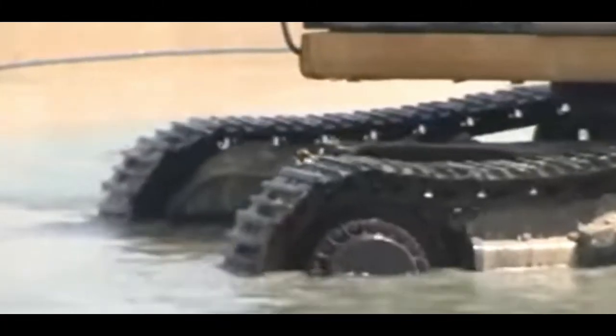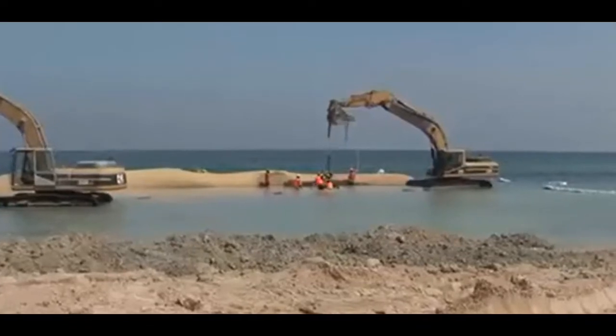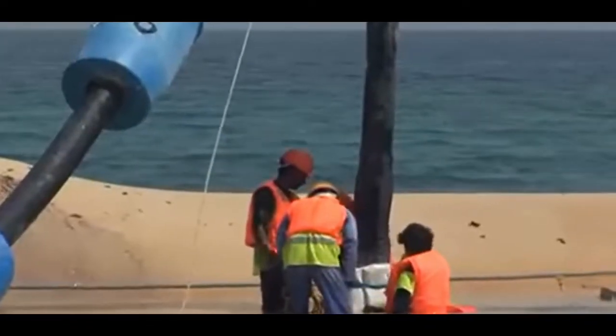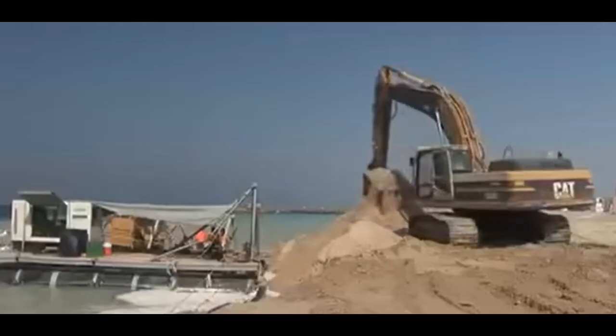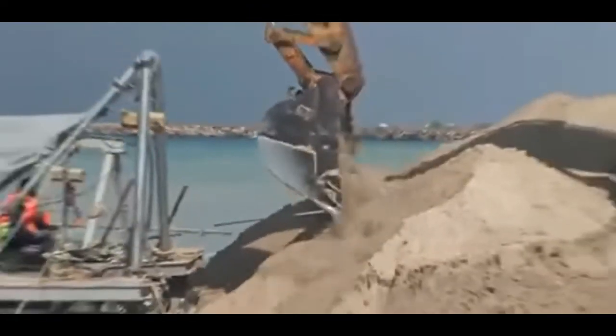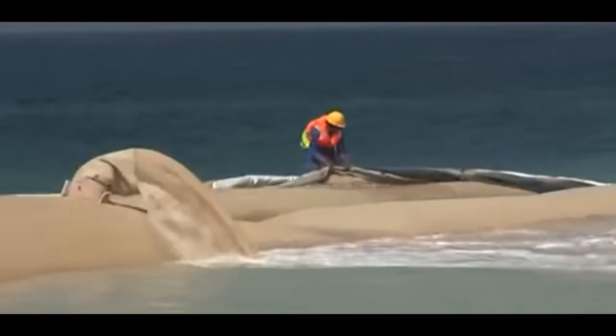An abrasion-resistant submersible pump with agitators and a hydraulic drive of 75 horsepower was hung in the middle of the air above the slurry pit. Then another two 6-inch and 8-inch self-priming trash pumps were used to supply seawater to the pit. Both pumps supply water at a rate of about 1,700 gallons per minute.